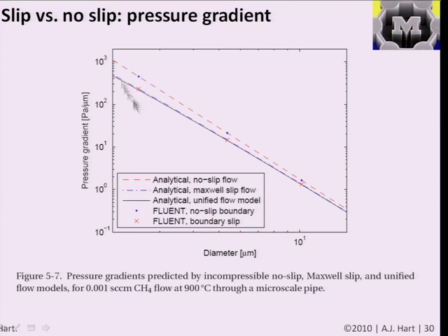In this case, if we had a pipe that is, say, 1 micron diameter, I think, to 10, we would have almost a 50% difference in the pressure drop through the pipe. And it says that the pressure drop in the case of slip flow would be a lot lower because the molecules are slipping. And if we go up beyond 10 microns, kind of down to the case on the previous slide of 50 microns, it's almost the same.